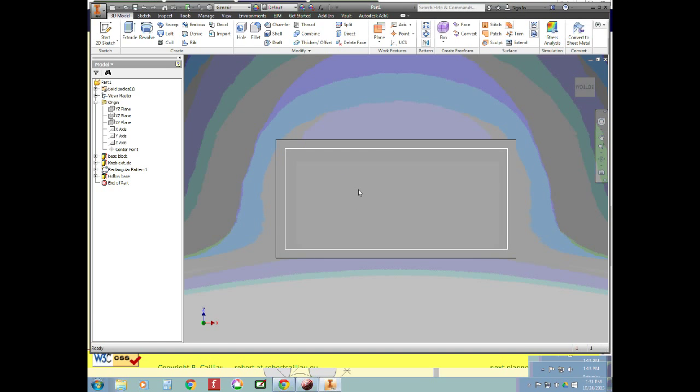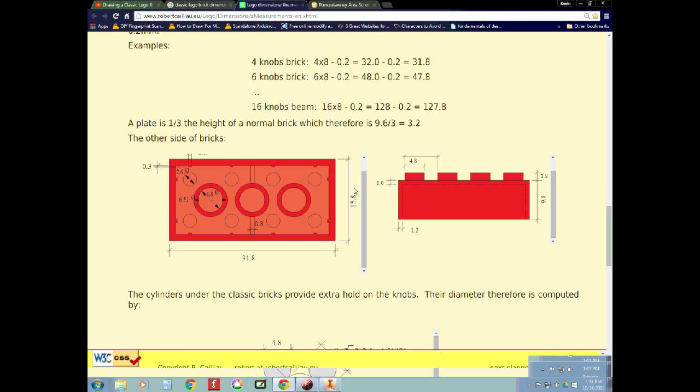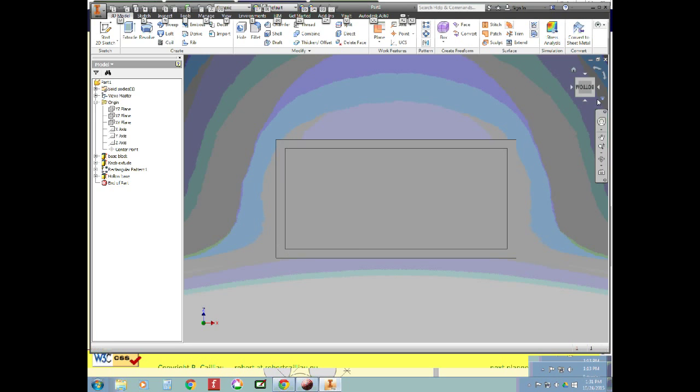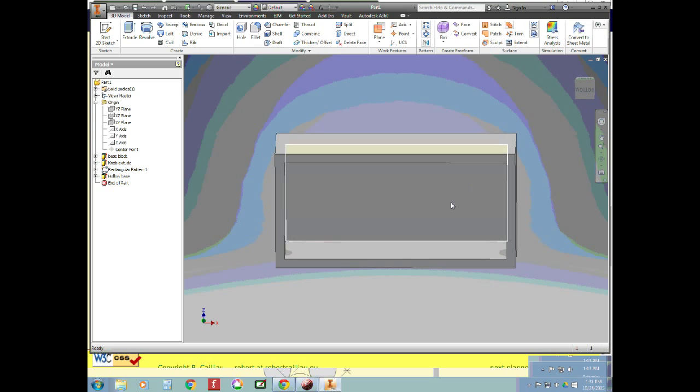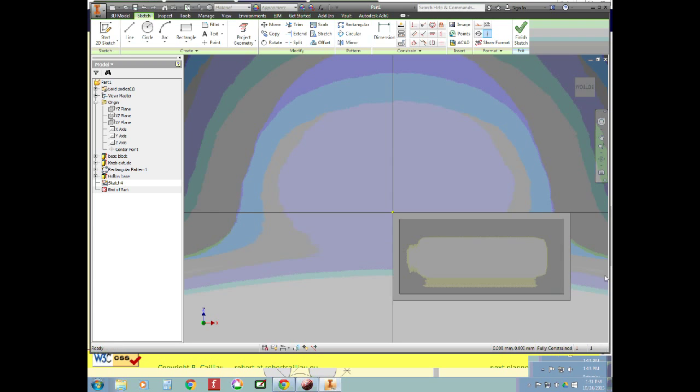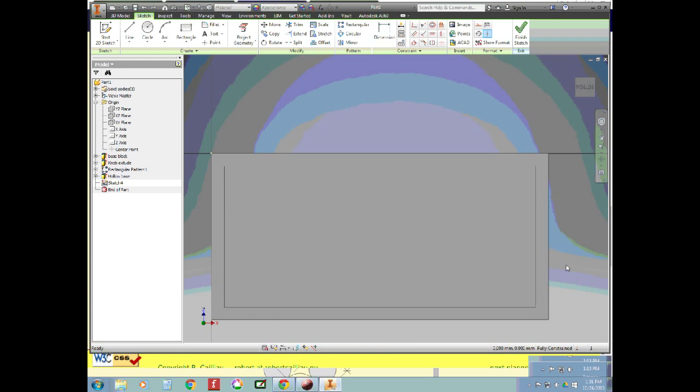We're going to do the cylinders inside first. That's these. And when we do that, then we want to pick, let me show you this. This surface right here is going to be the surface we draw on, and then we're going to extrude toward us. So again, if you right click and choose New Sketch, it picks the surface that you click on as the surface where your sketch is created.